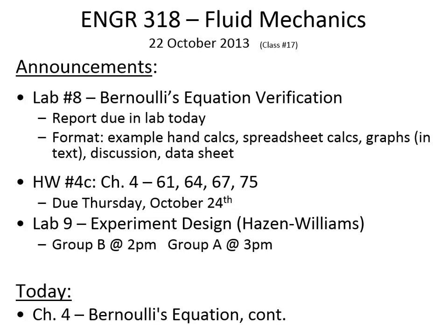When the throat contracted, remember that the velocity is high through the throat of the venturi. Since the velocity is high, that means this term is going to take on added significance. The pressure went down in the throat. Bernoulli's equation says that when the velocity increases, the pressure will decrease. And so this divergence is sort of the essence of Bernoulli's equation. When you see that the hydraulic grade line dipped down and then recovers, that's an expression of Bernoulli's equation.